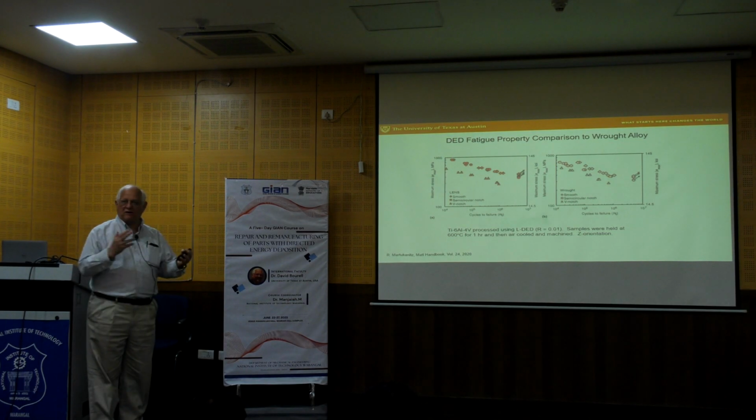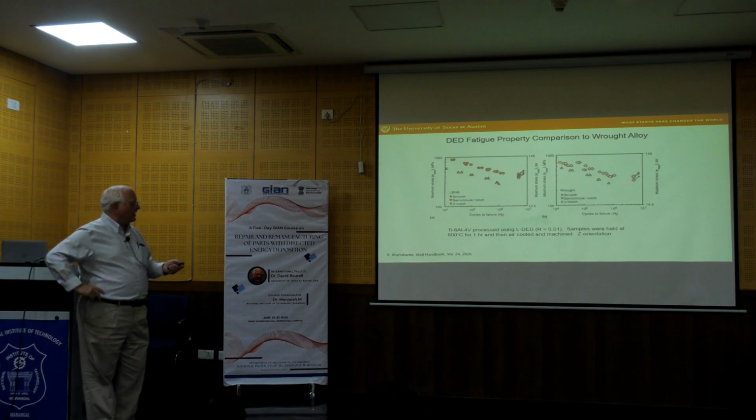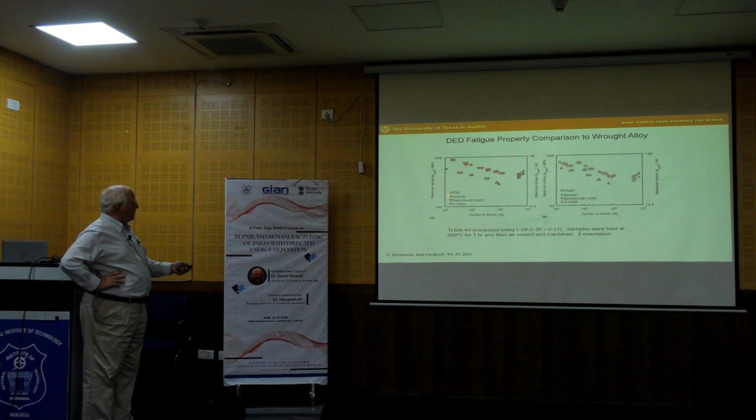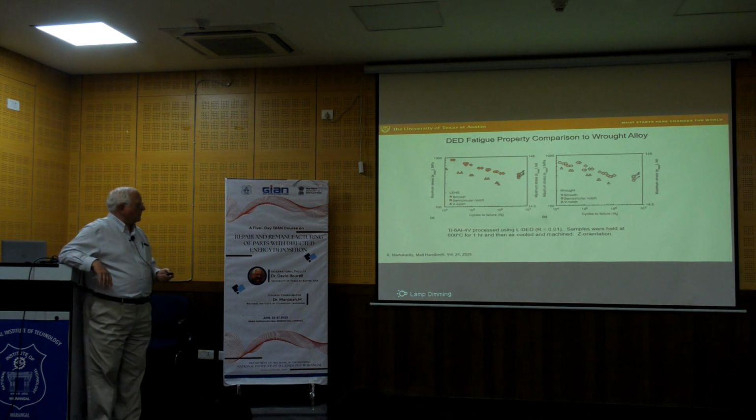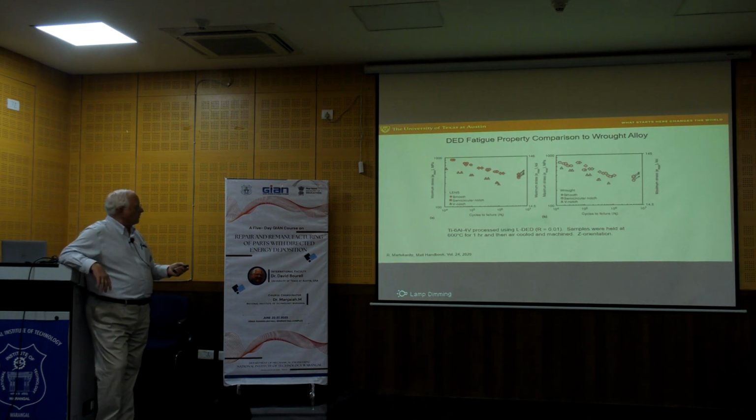I think it probably would have been a little easier to compare if they were on top of each other. But I think what you can see is the axes are the same scale. And so what we see is that it's basically the same kind of result for the fatigue, that the additive does very well. One might argue that the slope is a little bit higher here than it is here, a larger negative number. But certainly we start off pushing 1,000, in this 800 to 1,000 range, and the same is true over here.